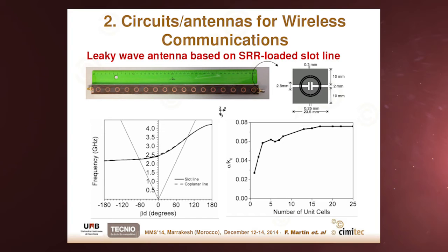The problem is that there is an important far-field cancellation due to the anti-parallel magnetic currents in the slots of the CPW. And by truncating the symmetry, you can improve the radiation efficiency of the antenna. And it was done in 2007 by skipping just one row of split-ring resonators on top of one of the slots.